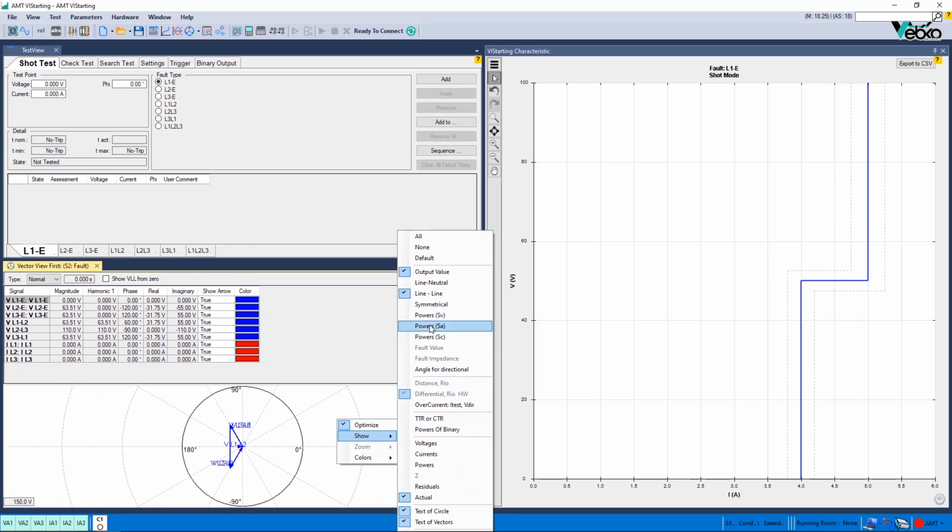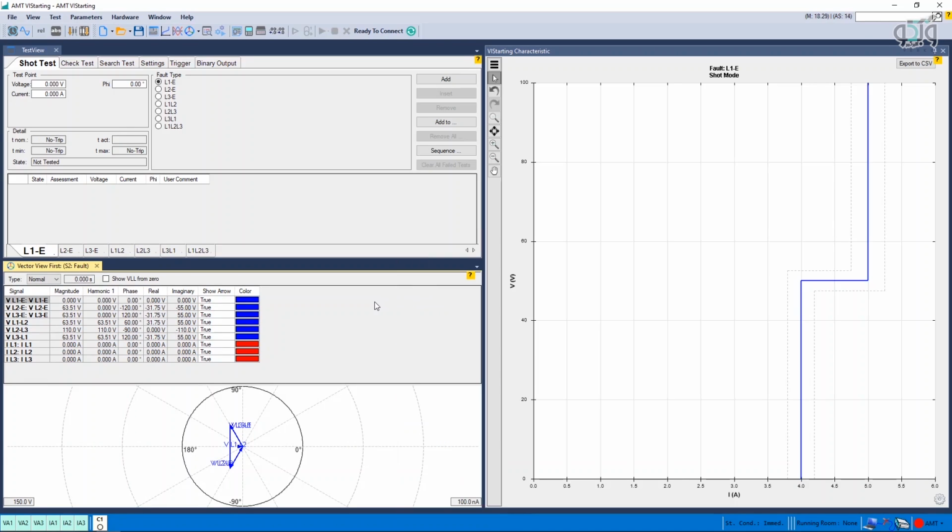Note that in the 51V function test, evaluation of detecting or not detecting faults is performed based on the test voltage and current amount, which can be voltage controlled or voltage restrained, and is used as a generator differential protection backup as well as for coordinating high current relays in power systems. To explain the difference between these two functions, characteristic curves and examples are used.